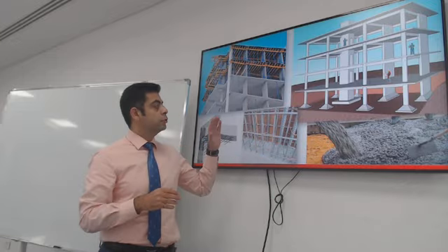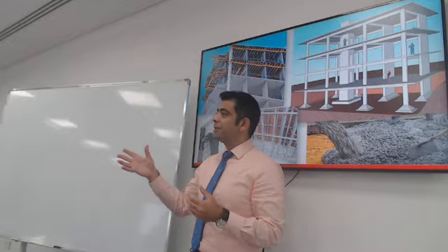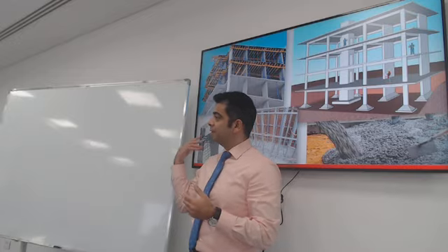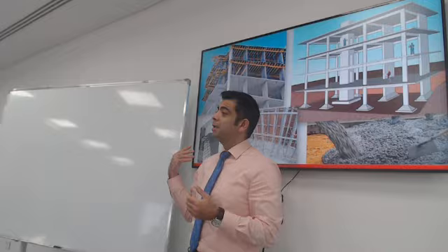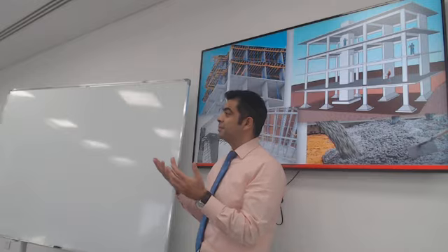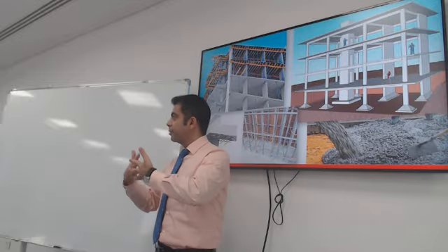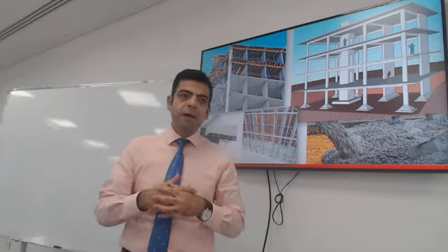We will talk today about how to design it under bending, and then next week we will get into the rest of the checks. What are the checks that you would do for a design of a structural beam made out of concrete? What are the steps? Shear, bending. Yes, bending, shear, deflection, so it's not excessively deformed.